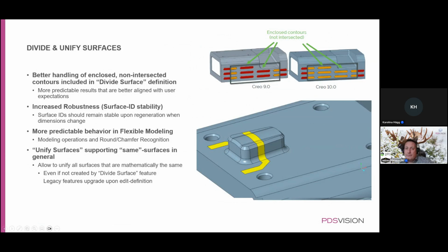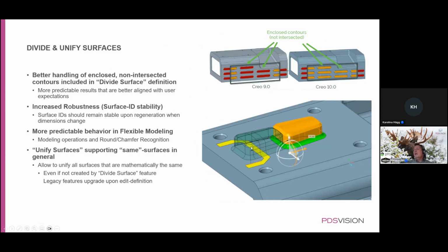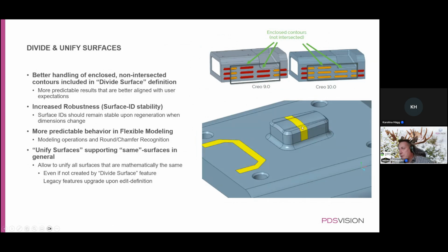Then on the other hand, I have a second bit on the next slide. If you have this kind of extrusion or bump in your model, and you want to transfer or move that using flexible modeling, with the tweak tool shown here, basically you just start dragging, and now it's 15 millimeters away. Then the question is, what will happen to this divide surface, which you saw also in the previous slide? So that will then remain, but still you have some stripe left in here. Using that